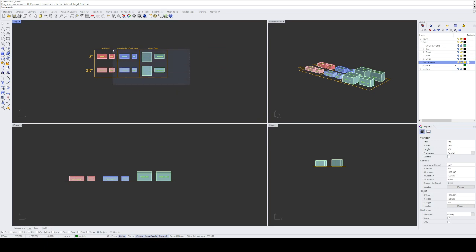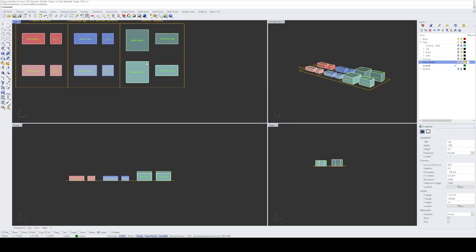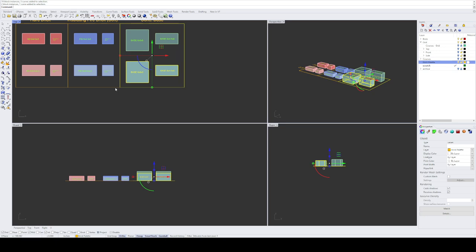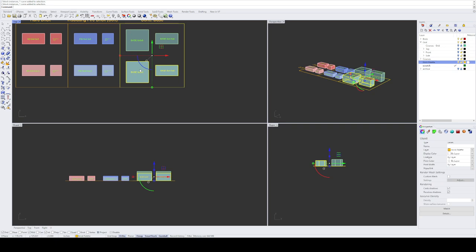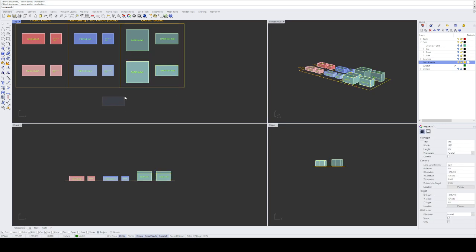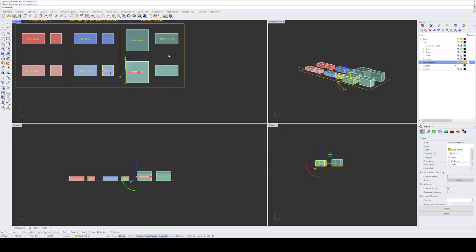Now you can again. Another thing that's super important is if you left click, you can select things. You can see the yellow highlighted. Now this is really important. If you go from left to right, you have to, anything that gets completely inside that box will be selected. But if you go from right to left, anything you touch will select. And that's super useful. And you'll see that later.